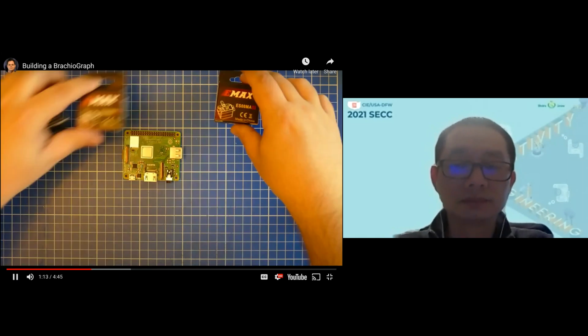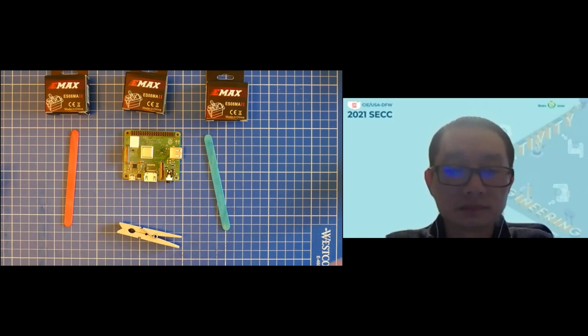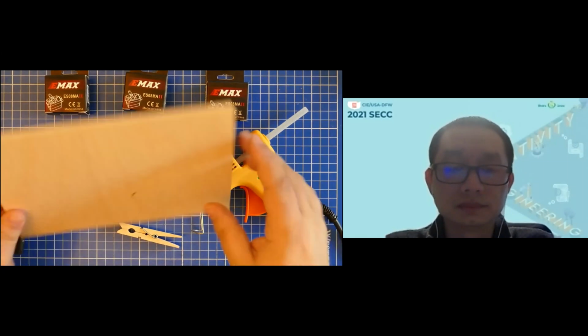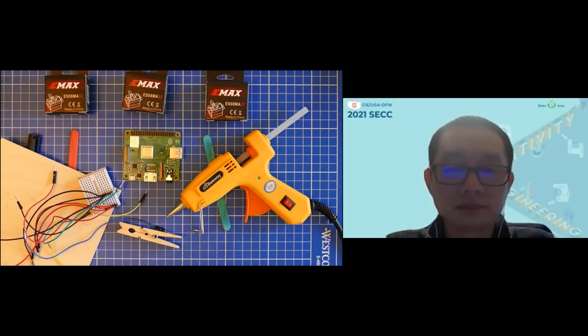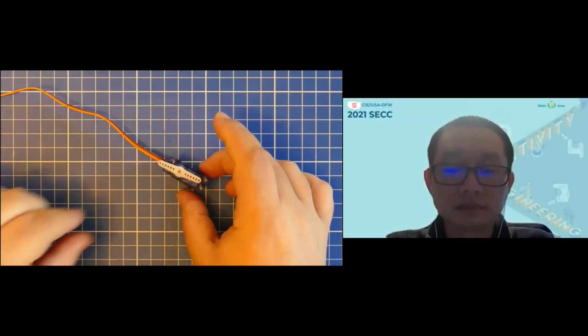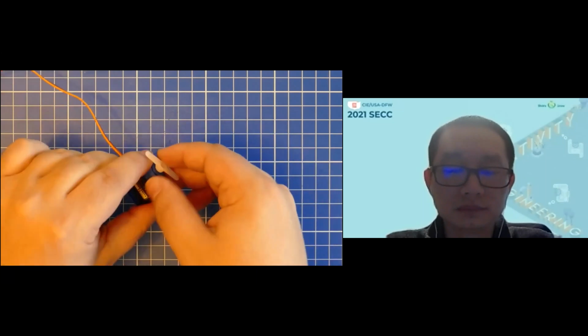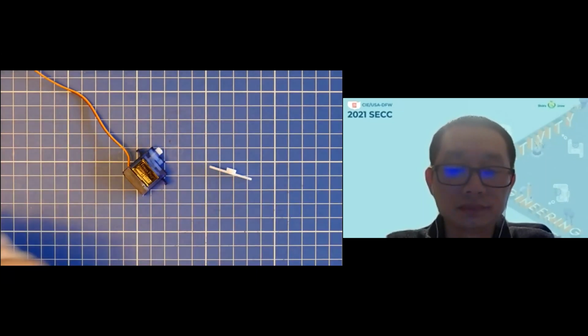3 servos, which I'll explain in a moment, 2 lolly sticks, a clothes peg, a pen, some glue, and I'd recommend a hot glue gun here, a base plate, any scrap wood or board will do as long as it's around 3mm thick, and some way of wiring everything together. A servo is a little self-contained package which allows us to precisely control the angle of its output shaft. The output shaft plugs into a little piece of plastic called a servo horn, which we can then attach to whatever we want. These always come packaged with the servos when you buy them.